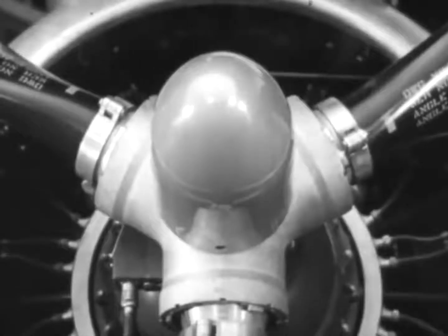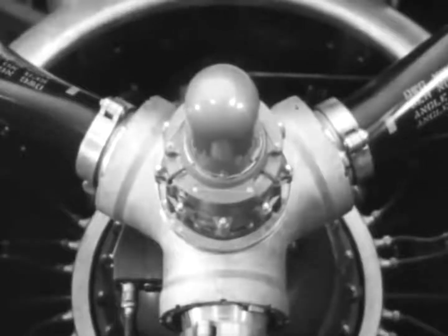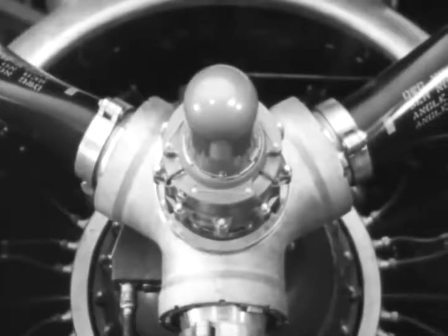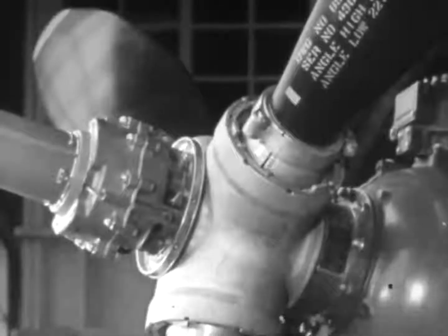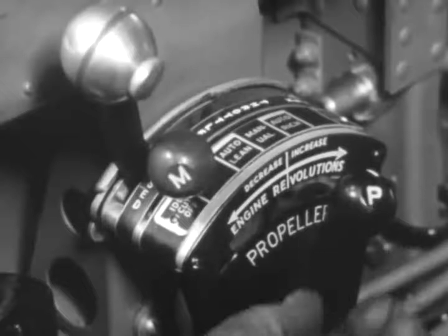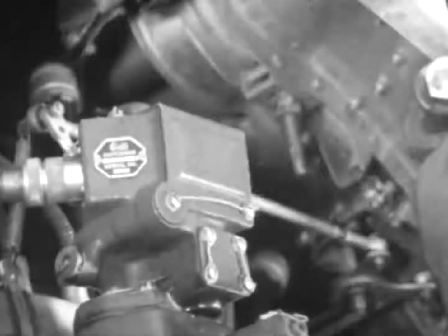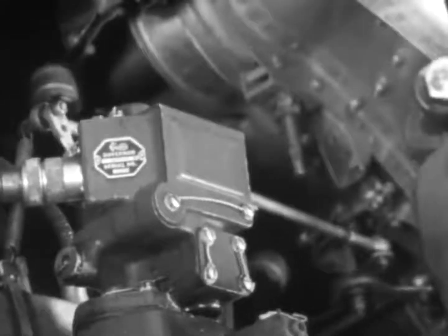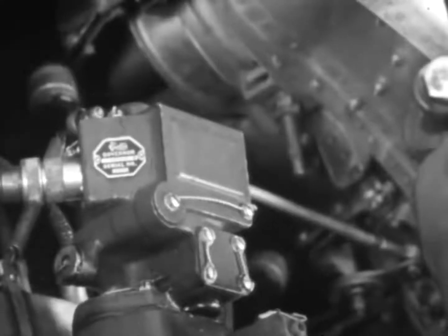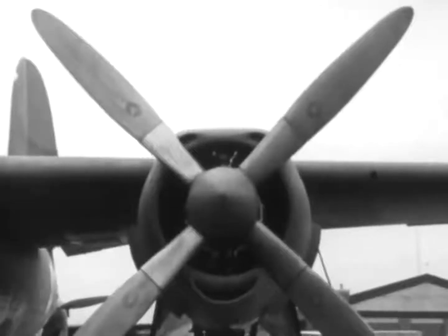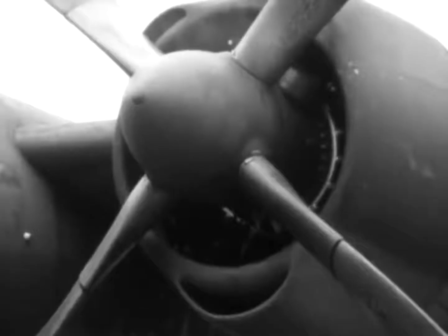Some aircraft mount still another type of controllable pitch propeller. The Curtiss electric propeller changes its pitch with a small electric motor mounted ahead of the hub. Constant speed operation is provided by a cockpit control which sets a governor. In the automatic position, this governor operates the electric switches to the pitch-changing motor. On multi-engine aircraft, a small switch in the cockpit allows feathering of the Curtiss propeller in flight to stop the engine and prevent damage.